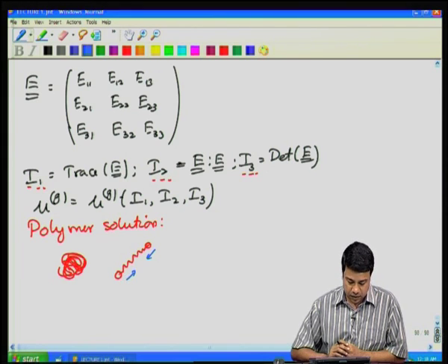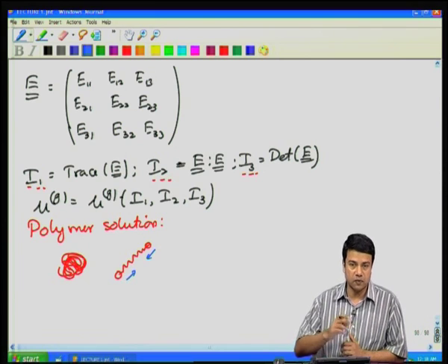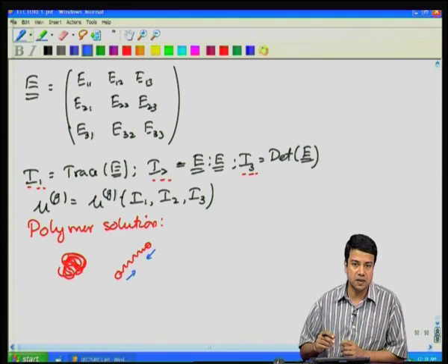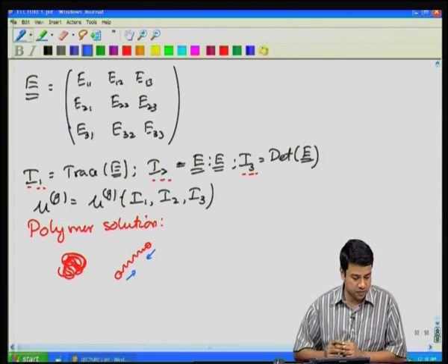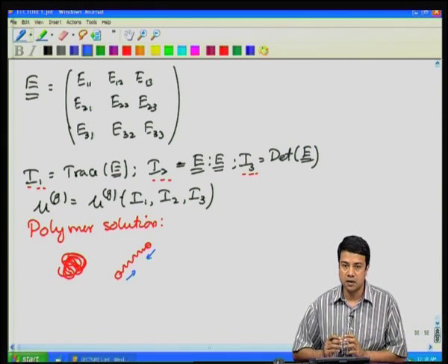Now, the distance between ends will roughly scale as the square root of the number of monomers that are there. If the polymer is in a perfectly coiled state in which it is a random walk, the distance between ends will scale as the square root of the total number of monomers in the polymer. In this case, it is not sufficient to just have a fluid viscosity. You also have a stress which is exerted due to the polymer.